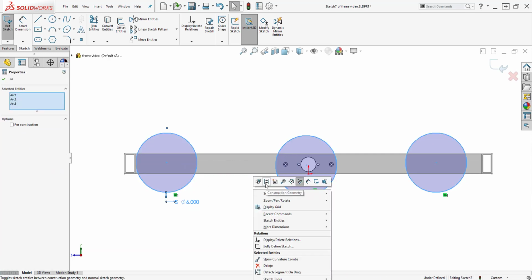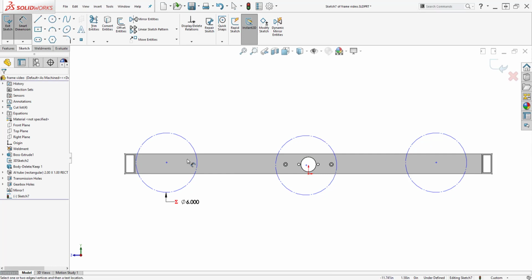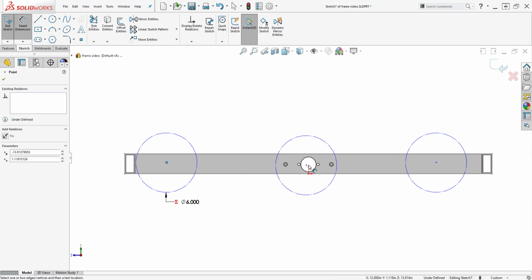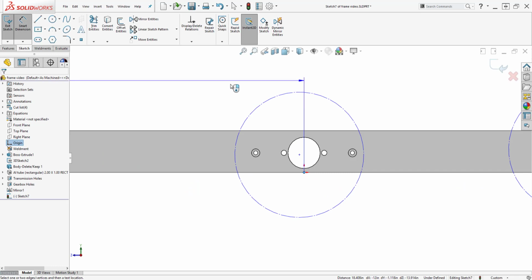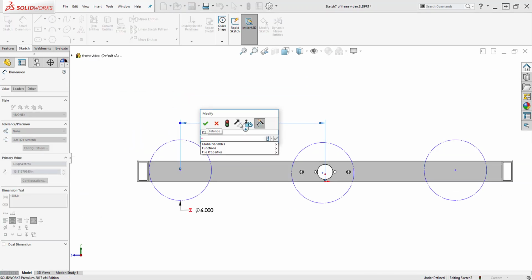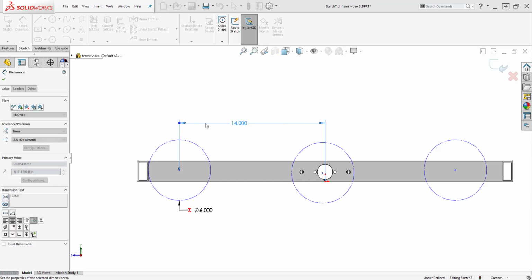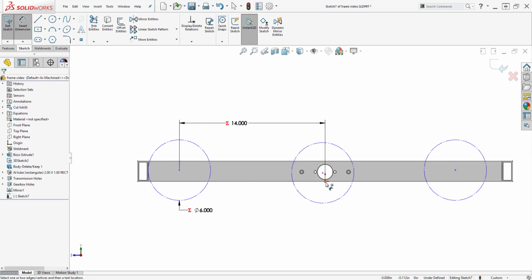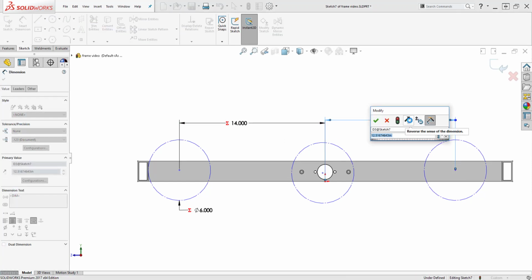On the SolidWorks side, all I'm really doing now is drawing a couple of construction circles that represent where my wheel diameters are going to be. I'm also showing you guys how I set my wheel center equations and wheel diameter equations up so that if I need to change anything later, I can. What you can do later is actually extrude these wheels and check later with the field elements and see if anything's going to hit the frame or if your frame is going to bottom out.